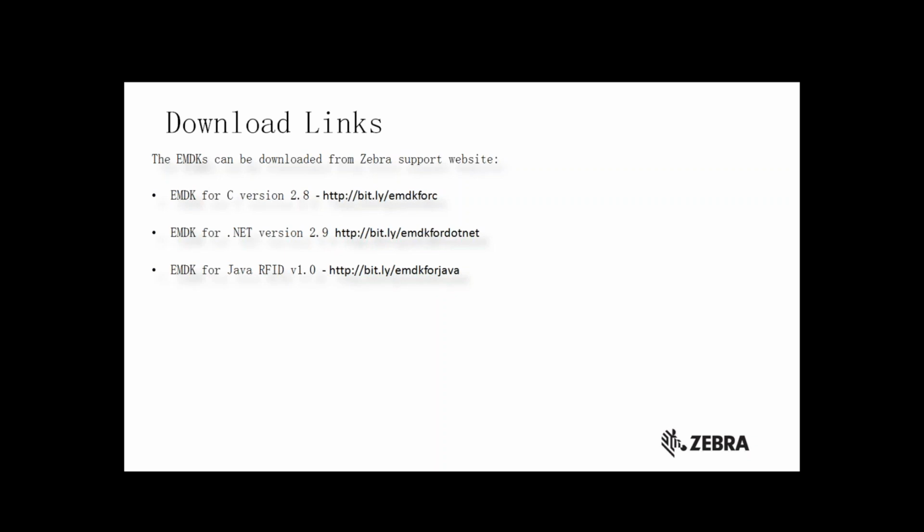The question regarding can we write more than 96 bits with the Zebra reader? The answer is yes, but it depends on the actual tag itself. If the tag capacity is set for that, we've had to write 256-bit tags, even 512-bit tags. It just depends on the tag you're writing to. The reader and writer will be able to address that.